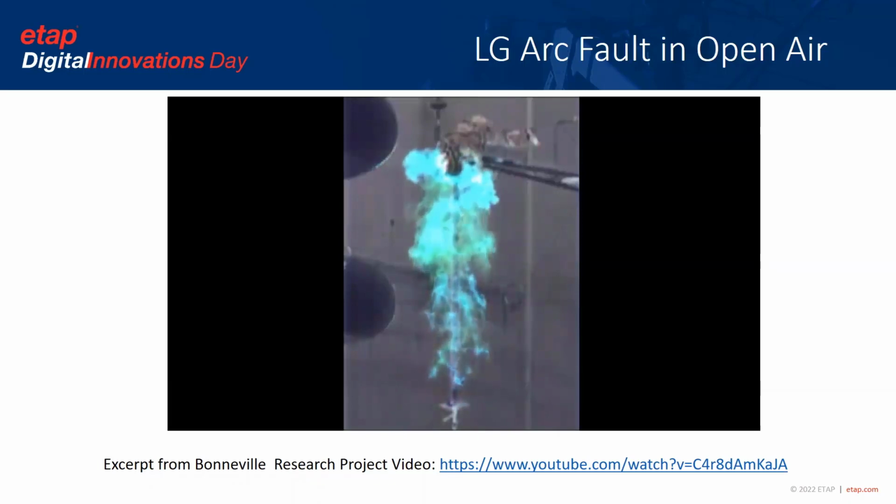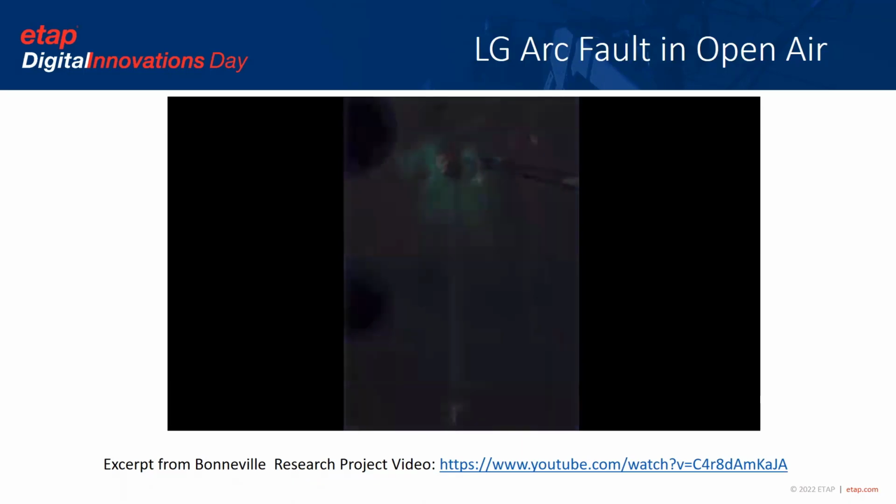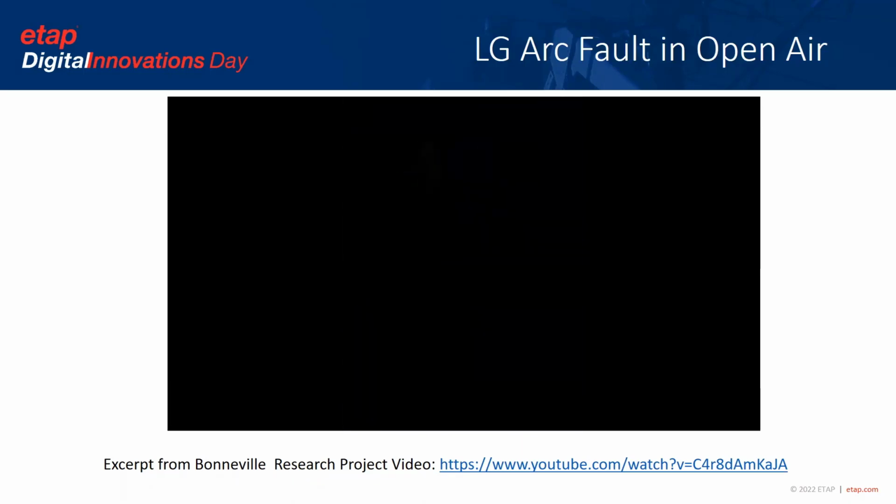The position of the electrical worker relative to the arc is critical. The arc heat flux is in fact not the highest at the current position of the mannequin. In its current position, the mannequin receives mostly radiation heat transfer up until the time the heated molecular cloud rose and made direct contact with the worker.